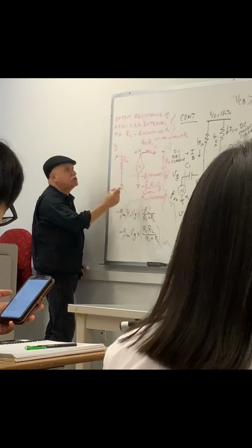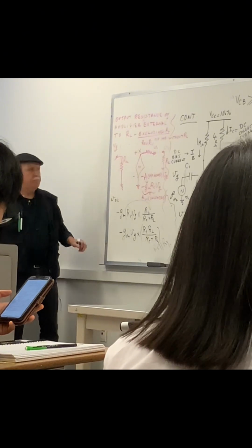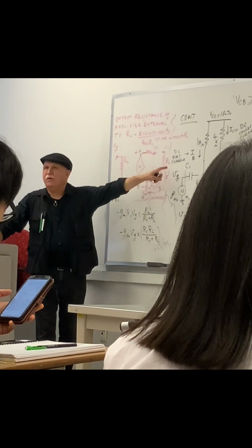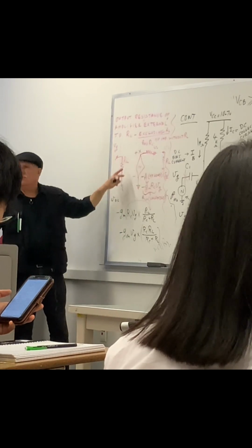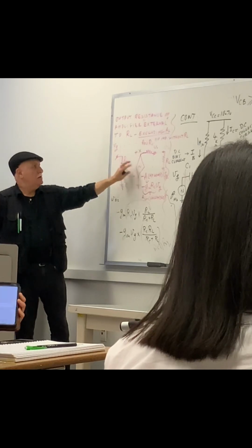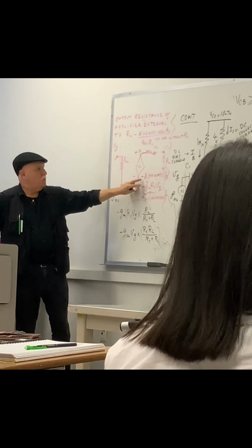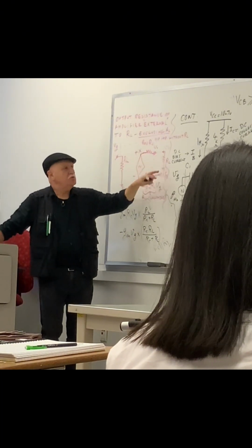Unloaded means excluding, I wrote in here, excluding RL. Any external parameter is kept outside the gain. Model it very simply, very easily, systematically, with one input impedance, one unloaded voltage gain, one output resistance, and then you see what comes next.